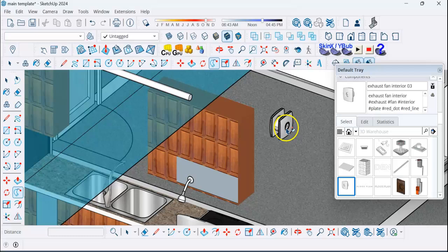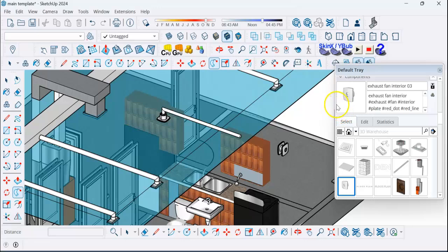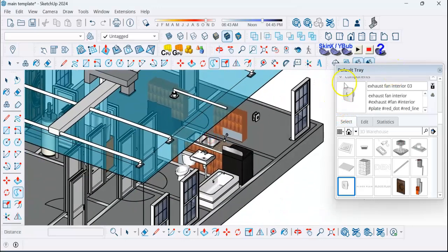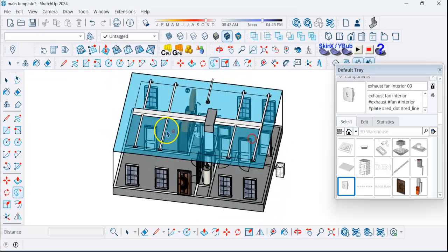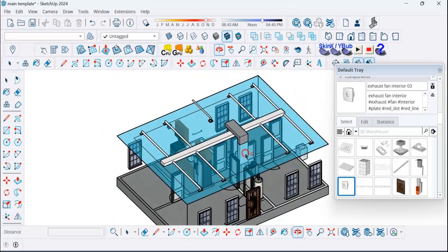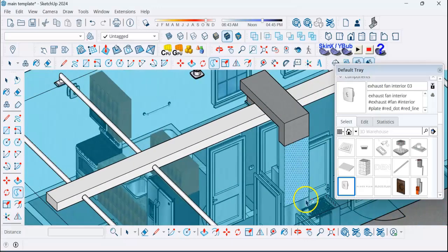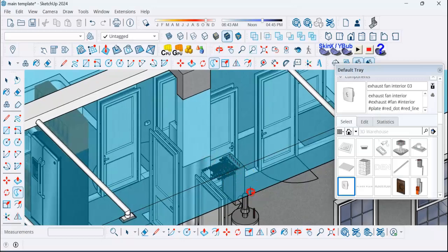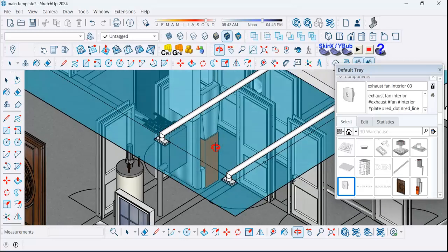The same with the air here. You never want to exhaust this into a space like the attic because that's bad, Lucas, because you'll build up moisture in the attic. All right, so now am I missing anything? No. The only thing I need to do is I've got my thermostat that would be wired and connected to the furnace. I'm not going to show that. You don't have to do that.